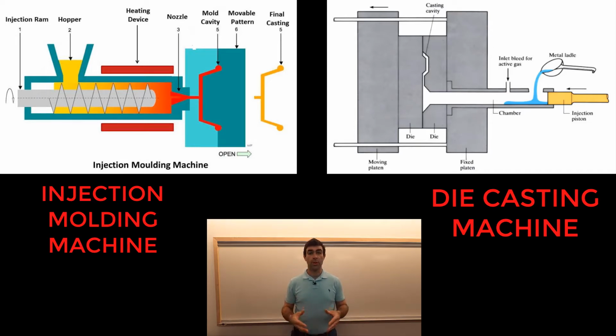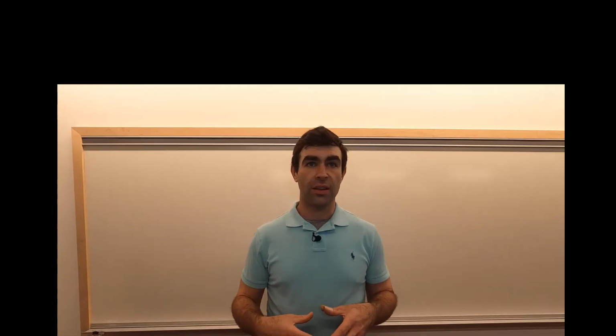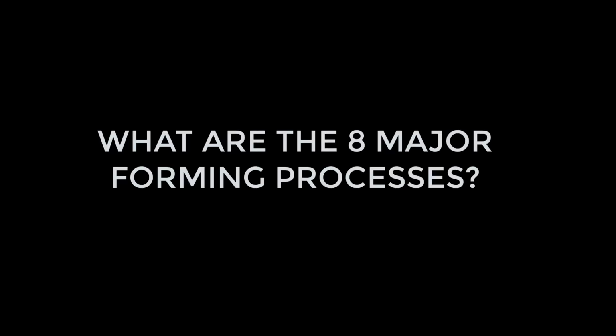Therefore, your equipment doesn't have to be as robust as something like a metal that has to be a lot hotter. So the dies can be made out of aluminum sometimes instead of being made out of tool steel. The hydraulics or toggles that hold the die halves together don't have to be quite as massive with plastics. This results in cost saving and easier changes in production.